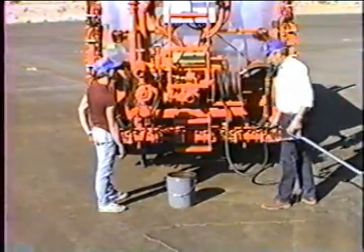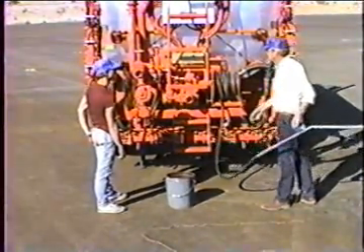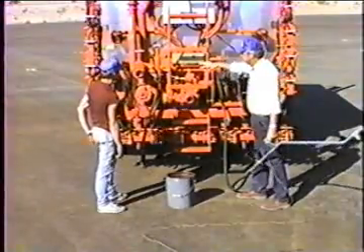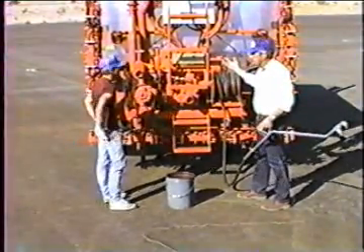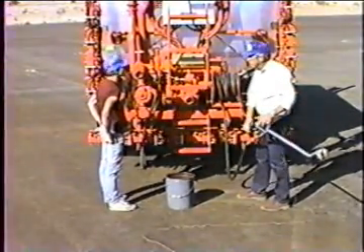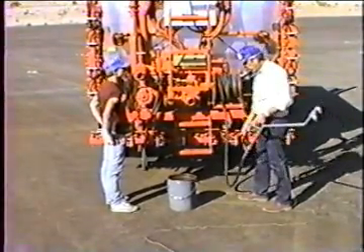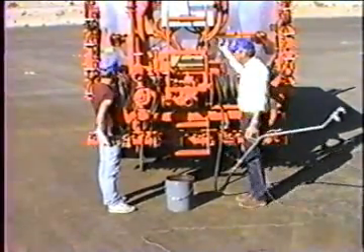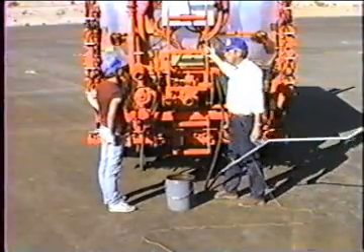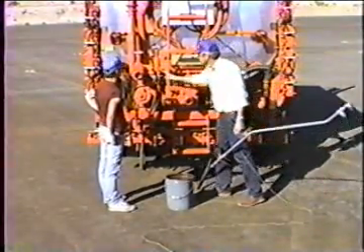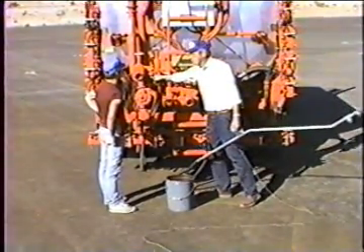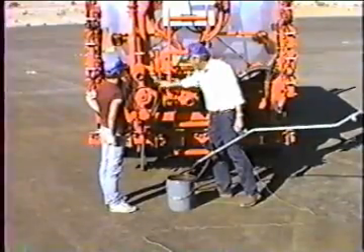Okay, an alternate way to do it is to do the first cycle, that is pump in reverse, open this, suck the asphalt back out of the handgun. Then close this, go to the cab, stop the pump, close the handgun valve, and open this valve.